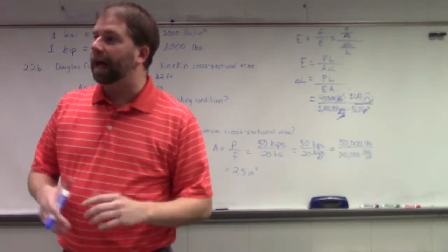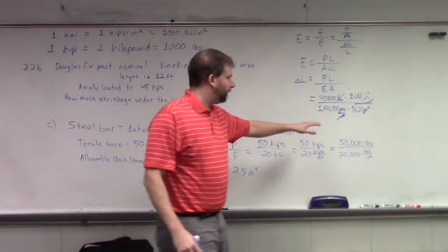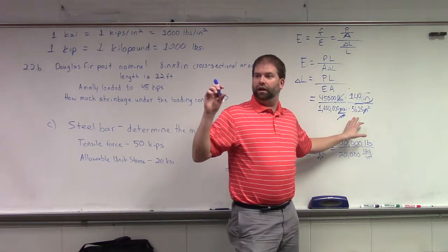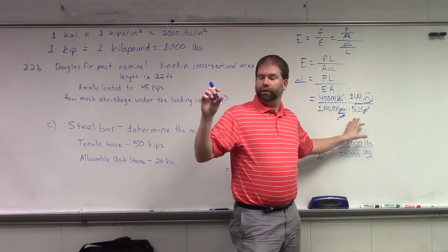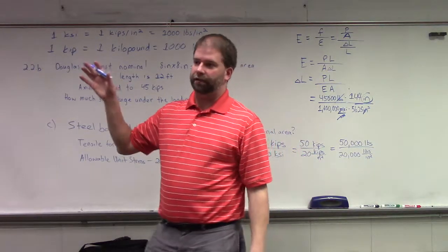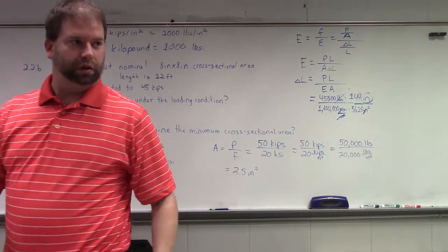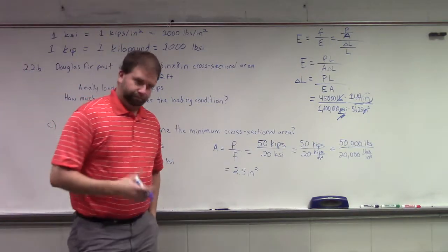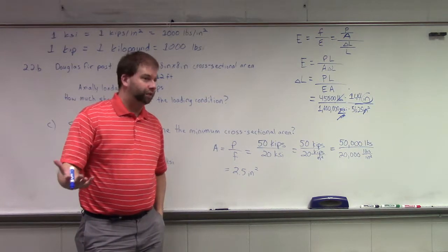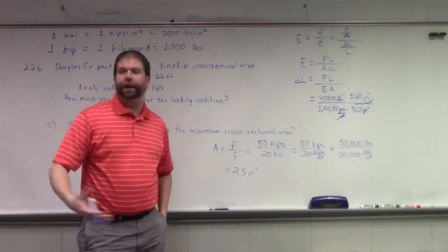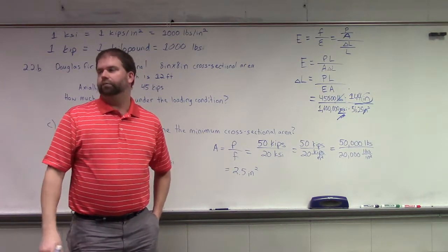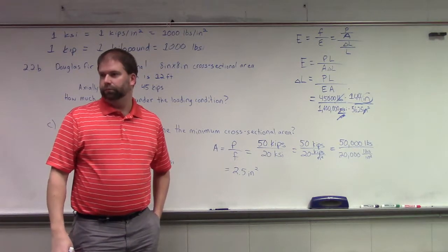So what we have to think about is what that means for us in the field. If we use 64 instead of the actual cross-sectional area, we might not put in a sufficient amount of joint material. So we may have an airflow issue, an issue with water migration. It's 9 thousandths lower. That's probably not a big issue over one event, but over the lifetime of a building it could end up being problematic, and if you have multiple of them in a series.